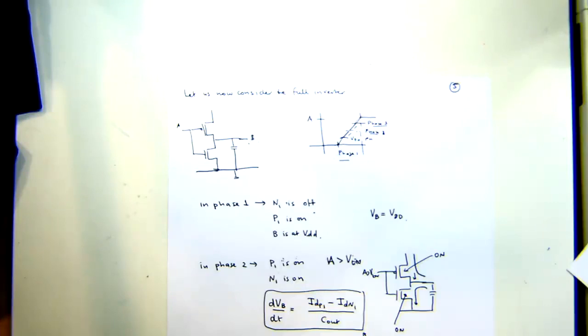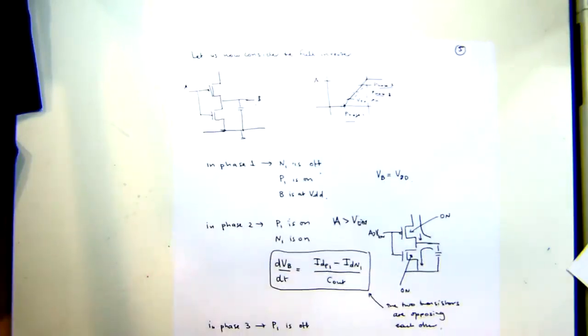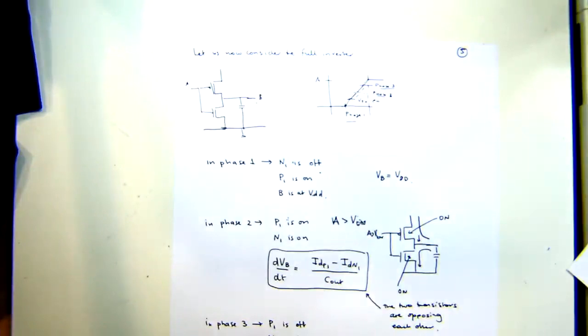the standard cell flow is essentially that, for an ASIC or a chip, you write what you want the chip to do in Verilog. That's pretty standard. It's the same as FPGAs. The only difference is that instead of sending the bit file to an FPGA to configure the switches in order to implement the logic in those lookup tables, the compiler goes to a library, which is usually written by the vendor, or I think it's some company called Artisan.